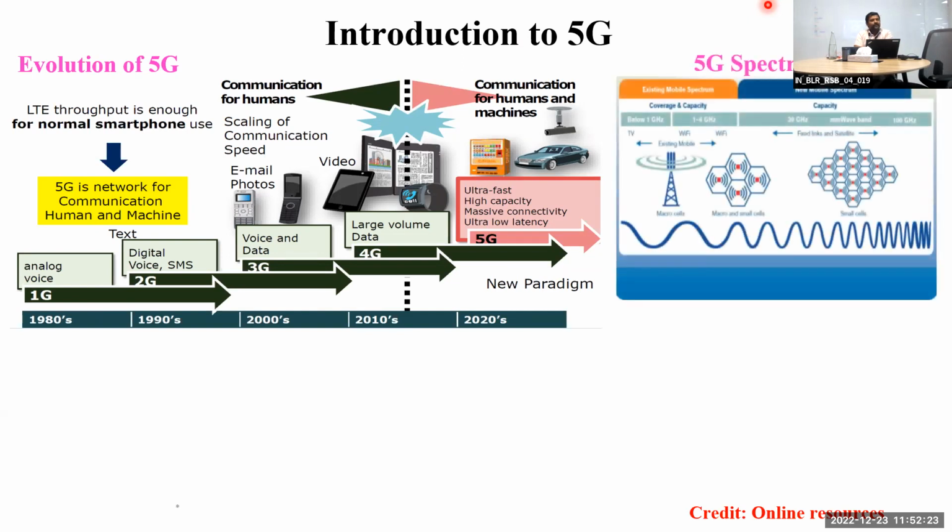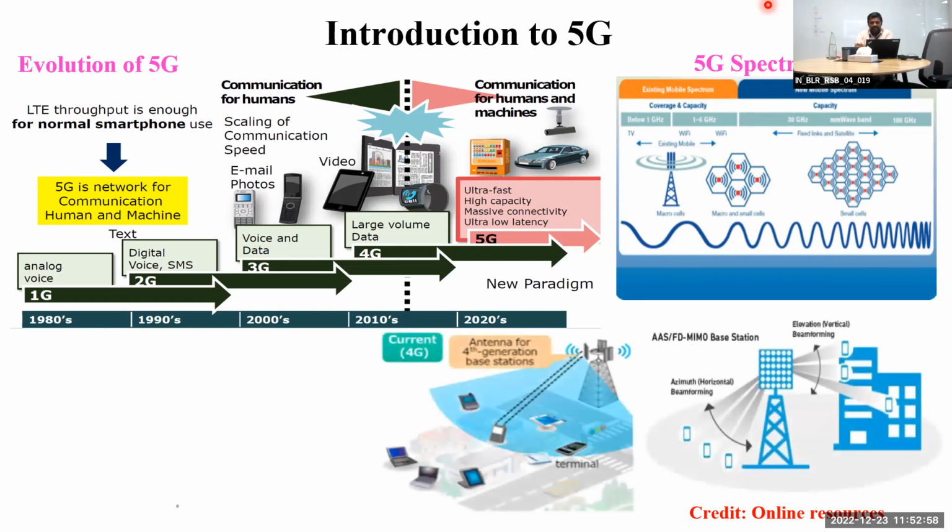And in 5G, the advantage is that they leveraged some of the frequency bands as well. For example, in both the sub-6 as well as the millimeter wave, they got a huge amount of spectrum, I would say. In the sub-6, approximately 200 megahertz is leveraged, but each operator may get up to 500 megahertz, especially in India. And in millimeter waves, you have plenty of spectrum. Some are licensed, some are non-licensed. So you have good flexibility to cater for the first item in 5G, like enhanced throughput.